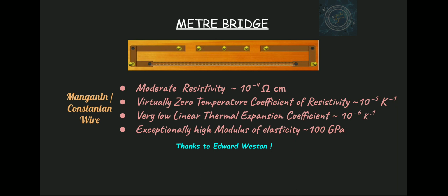So you can see that using this method, when you have a resistance P in the top left and a resistance Q in the top right, using the Wheatstone bridge formula for the null condition, you can have P by Q equal to L1 by (100 minus L1), which is obviously measured from any side, left or right. Here I would prefer the left side, just as convention. So whenever I say any length, remember that I am talking from 0 at the left to that length.